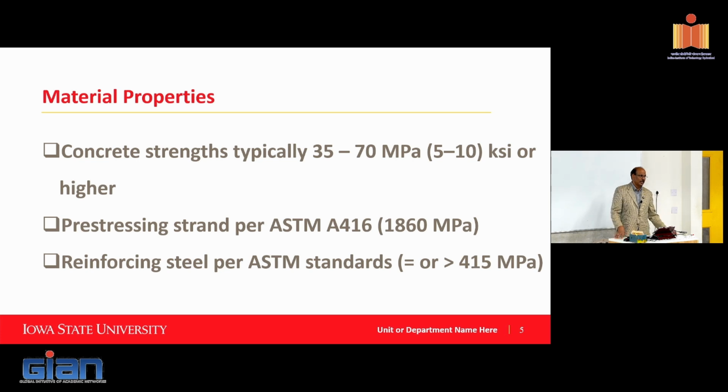when they release the strand, one of the things with the precasters is that I talked about the 24-hour cycle. So if there is pre-stressing involved, the load has to be transferred to the concrete within 24 hours. And whether you can transfer the load or not depends on how strong the concrete is. So the higher the strength, the more likely that you will achieve that.